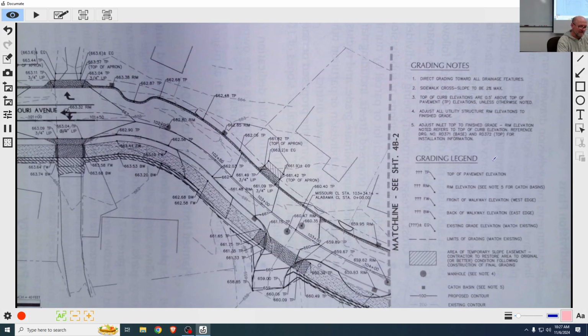So the road pavement, I guess, or the gutter pavement. But they say the top of the pavement, and if that means the top of the road, it dips down. The road typically has a crown to let water run off of it and into the gutter, and then the gutter slopes the other way to drain into the storm drains. So the top of the road, apparently, the curb has to be 1/2 a foot above that, so 6 inches.